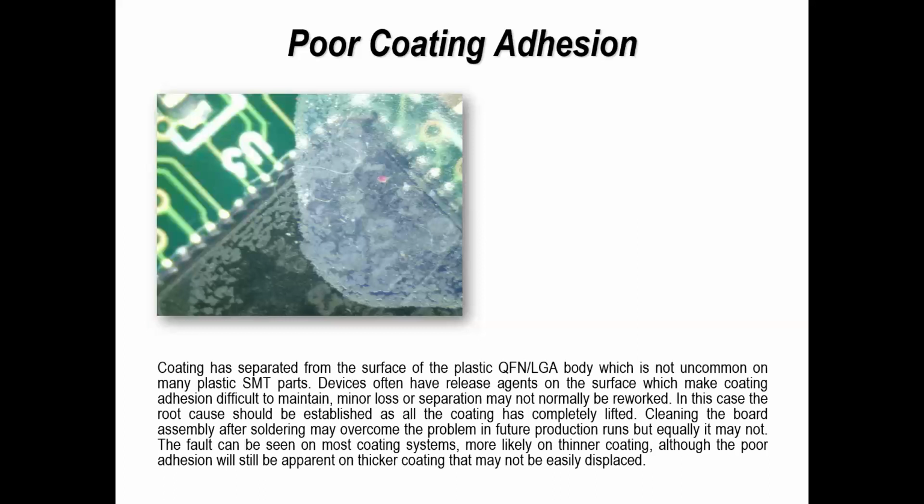Whether you need to or not, how could you? Well, one of the things that can be done to clean packages like this is use a plasma. This is a process which is available with some coating companies. You're creating a plasma gas that's attacking the whole of the board, but just at the surface. It's literally doing a cleaning operation on the surface to improve the adhesion.